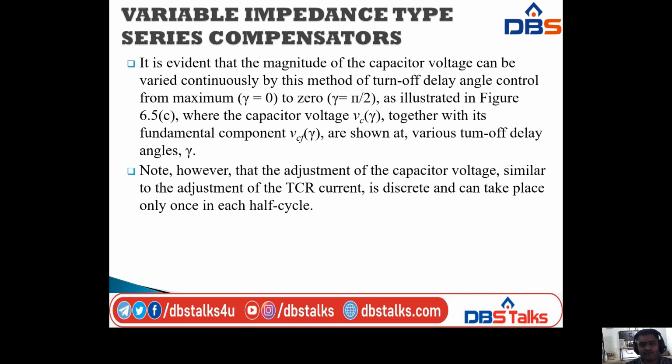Note, however, that the adjustment of the capacitor voltage, similar to the adjustment of the TCR current, IL of t, is discrete and can take place only once in each half cycle.